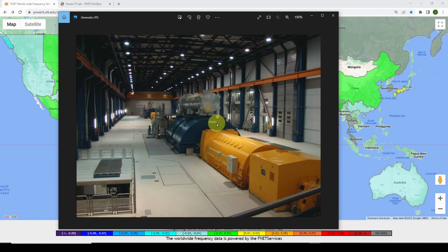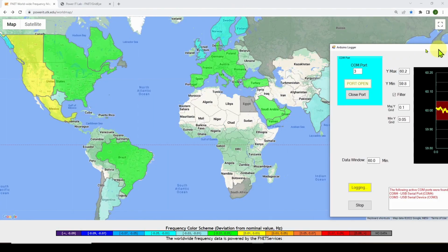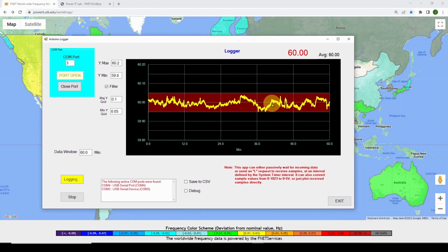So it's very important that you make sure you have enough generation and that you maintain the right speed, because speed is a very good indicator of how overloaded or underloaded your system is, all right? Just like measuring the speed on your speedometer of your car, if you're supposed to be at 60 and you're at 30, you know that you're overloaded. You can look at the speedometer and say, hey, wait a minute, I want to be at 60, but I can only get to 30. You know you've got a big problem. Same thing on the power system. So that's why this measurement of frequency is such an excellent indicator of the status of the power system.